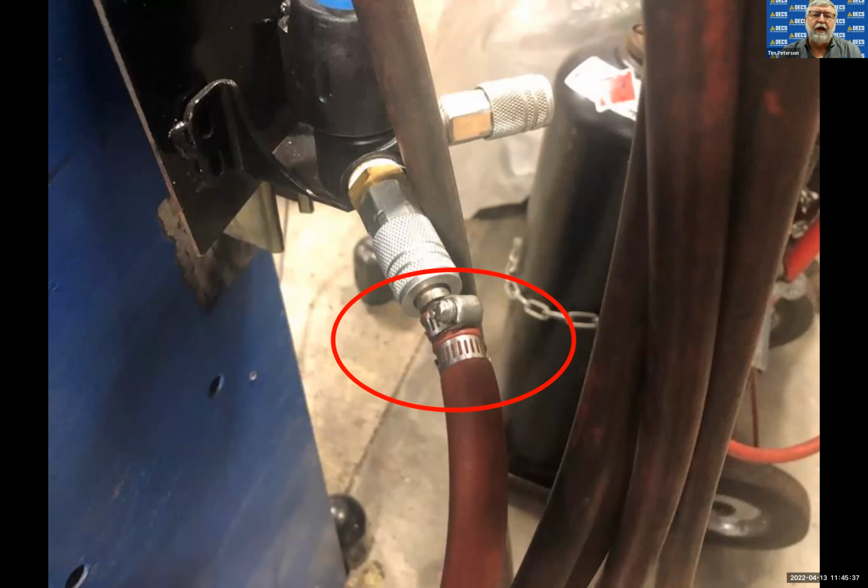Air hoses, pressure lines, and how they're attached to the devices, to the connection points. In this case here, a quick coupler. This little clamp that you see here is called a screw worm clamp or a water clamp by most hose clamps. And they can only be used on water lines, not on pressure lines like on an airline. And if you look close at this picture, there's two of them there. Probably because the first one wasn't doing the job correctly, because you don't know how tight to tighten it. But if you look at the very first one, or closest to the bottom, you can see it's actually cutting into that outside insulation of that airline. In other words, it could be doing damage to it.